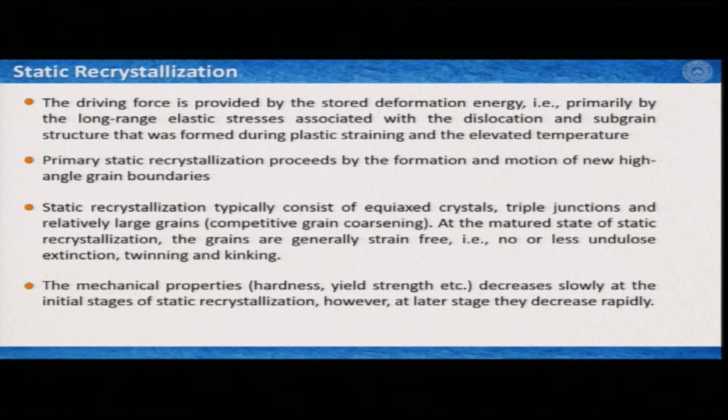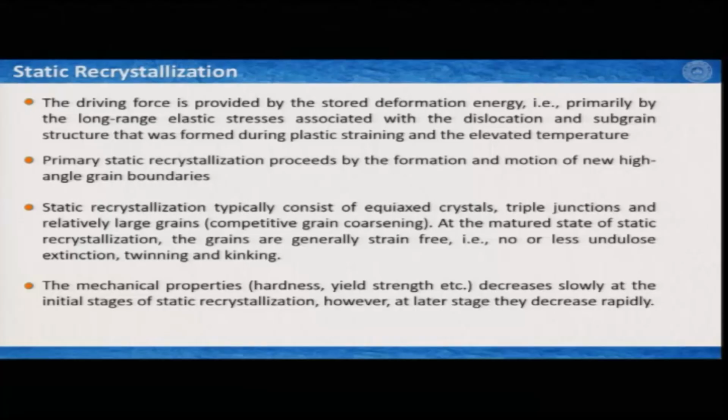Static recrystallization typically consists of equiaxed crystals. That means the crystals are mostly of similar size. The microstructure is also characterized by triple junctions, and the grain size is relatively larger, and this grain growth is known as competitive grain coarsening. And at the mature state of static recrystallization, the grains are generally strain free. As I talked about, the process is called annealing. So, you do not have any internal energy within the grain.